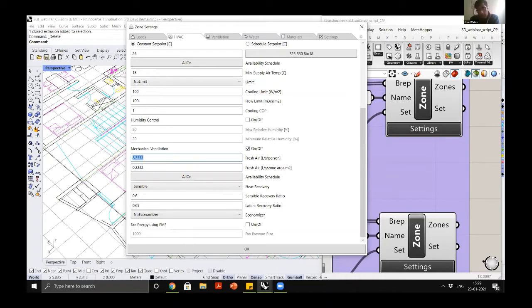Another thing that you can add in this tab is the energy recovery and heat recovery ventilation. You can read about that in more detail, what these systems are. They are basically there to reduce or pre-cool the air that is coming from the outdoors. Using heat exchanger, you can assign the efficiency ratios. If again you have specifications of the products that you're going to use, you can try with these efficiency ratios and see how much energy you can save.